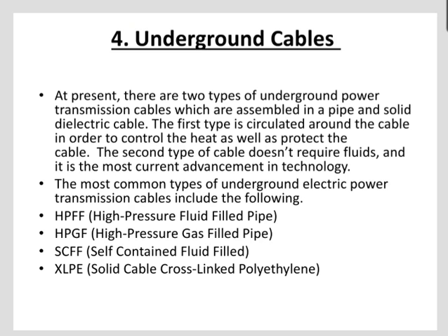There are some advantages of undergrounding. That is, it is less subject to damage from severe weather conditions. The second one is decreased risk of fire and overheating. Overhead power lines can draw high fault current from vegetation to conductor, conductor to conductor, etc. Reduced range of electromagnetic field emission into the surrounding area, so that depending on the depth of the underground cable, greater EMF may be experienced on the surface.